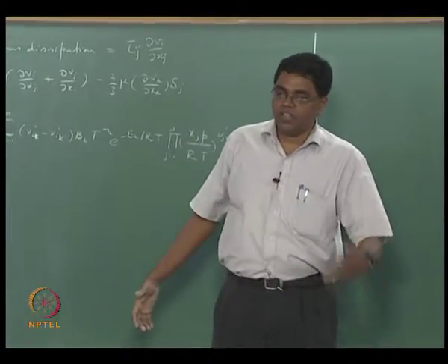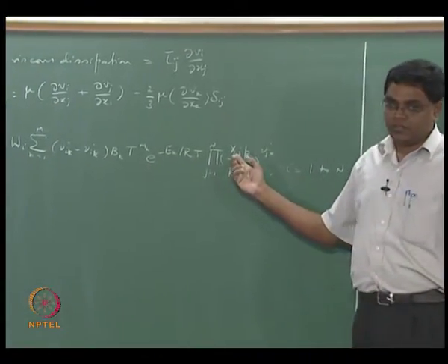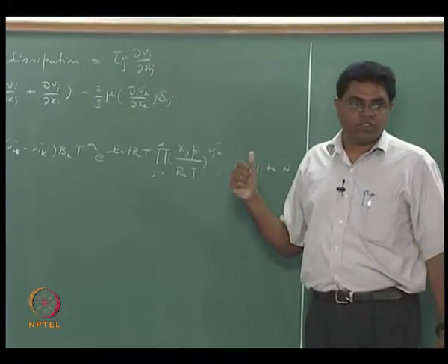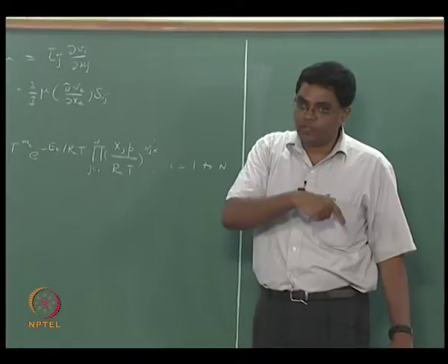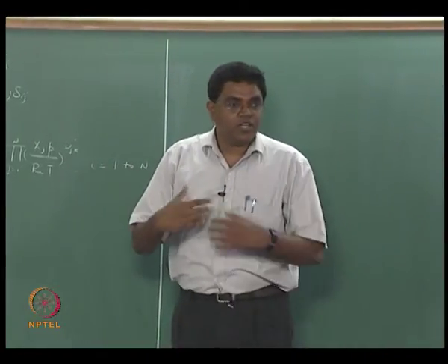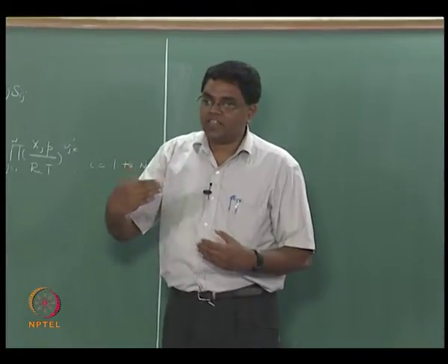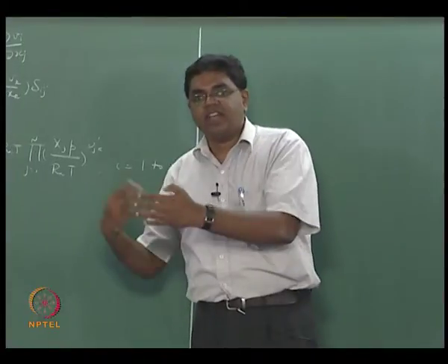The set of previously agreed unknowns was concentration. This is a mole fraction. Of course what we enumerated first was the mass fraction Yi, but the moment you actually use the multi-component diffusion equation, that equation was on grad xi, so we had to now start reckoning xi as our unknowns, and therefore we have to have a set of equations that relate xi and yi.